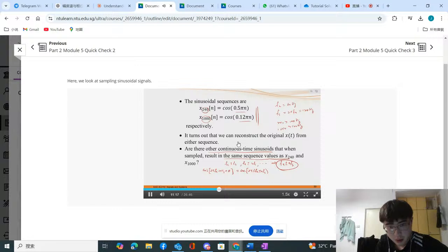So it's an integer multiple of the sampling frequency, and then maybe I should use this one as m here, to differentiate from the other n ts here, right? So when I multiply that, I get n ts plus a phase angle. All right, so I cross multiply, I end up with cosine 2 pi fa nts plus or minus 2 pi m fs times nts plus a theta. Okay, so over here, you can see that fs times ts is equal to 1. So you end up with 2 pi